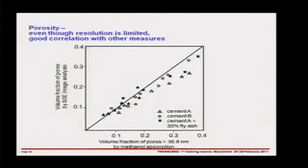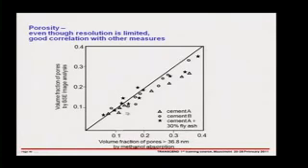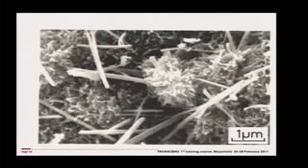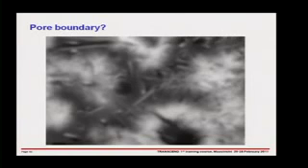And when we made a series of measurements over several different cement types, and we measured the volume fraction by image analysis, and we compared it with the volume fraction of pores above about 40 nanometers, so we're really looking at the big pores that we could determine by methanol absorption, then we found there was a pretty good correlation between the two. So it's not the best technique due to this pore boundary effect, but despite that, it does seem to give you reasonable results which are free of operator error.